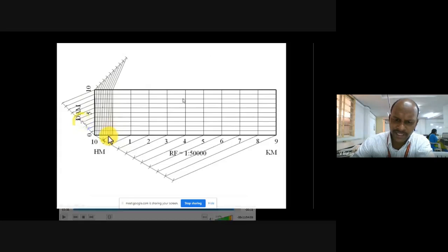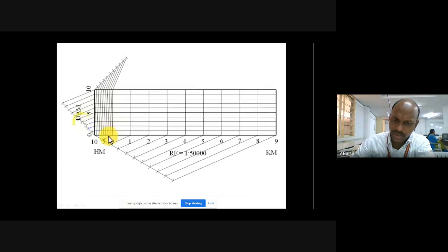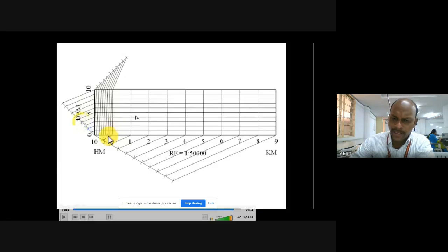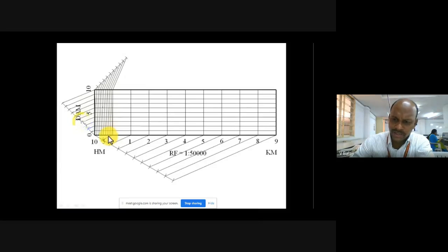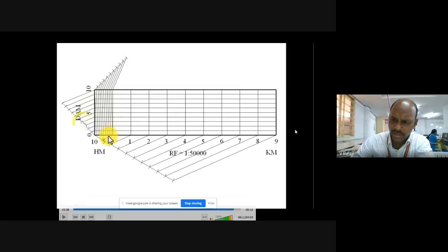In the calculation part there is absolutely no difference. But construction-wise, in case of diagonal scale, we need to take more height to represent the third unit on the scale, and you need to remember carefully the relation between main unit, subunit and its subunit. In this way, you can construct any given problem.